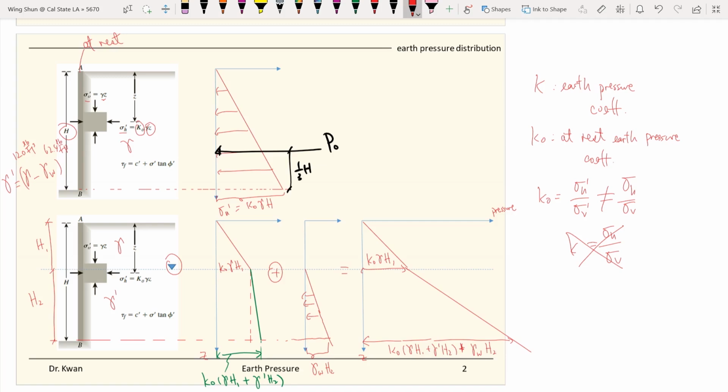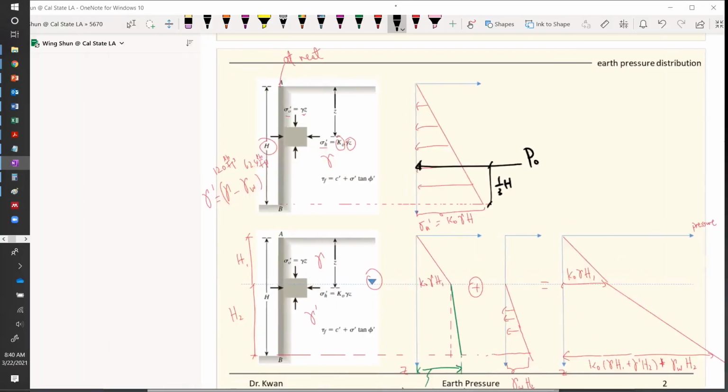And here maybe is a better time to look at the resultants, the locations of the resultant for us. You have different shapes of area, and you need to find the locations of the centers of those areas, and then take a moment, and then we will find the resultant location for the overall retaining wall design. And we will talk about that more in examples.